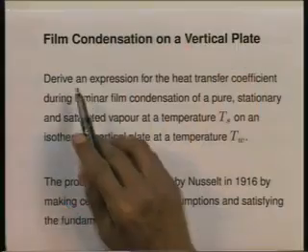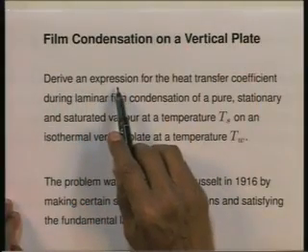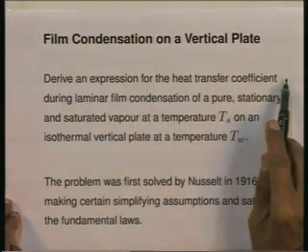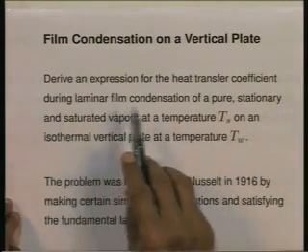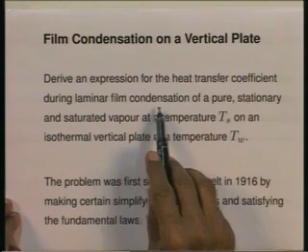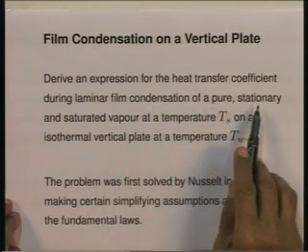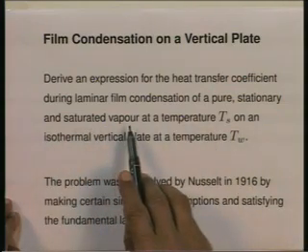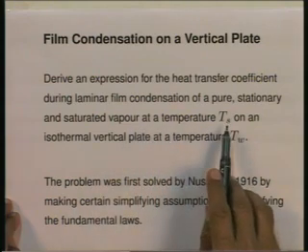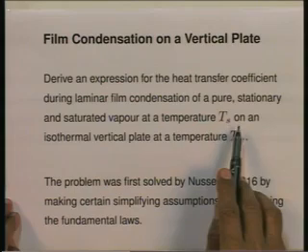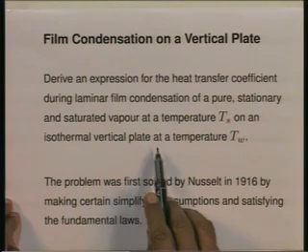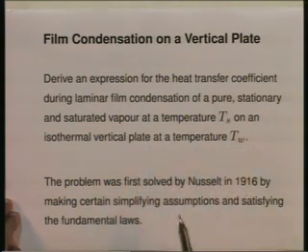We are going to derive an expression for the heat transfer coefficient h during laminar film condensation of a pure, stationary and saturated vapor at a temperature T_s on an isothermal vertical plate at a temperature T_w. That is what we are going to do.